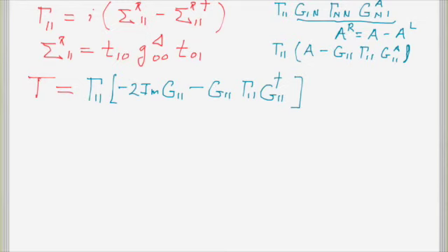That's why we said, if you just wanted current, which means you just need transmission, the only thing you need is G_11. And so that's the recursive Green function algorithm. That's the way we go about it if we have any problem that's not numerically trivial, to calculate what we need: the Green functions in the device, the transmission, and the electron density. So I guess that brings us to the conclusion.